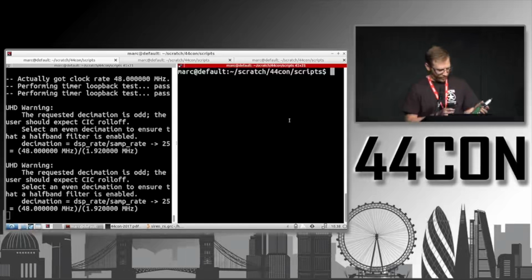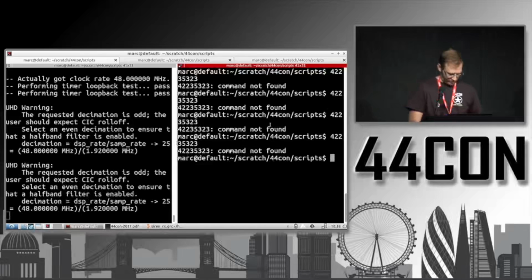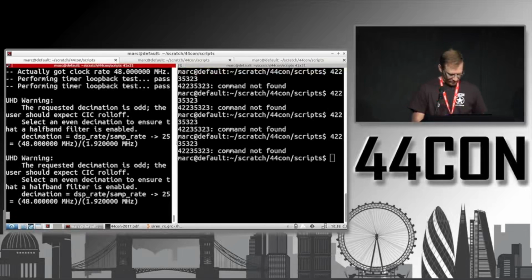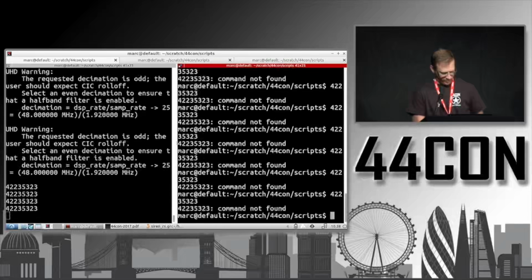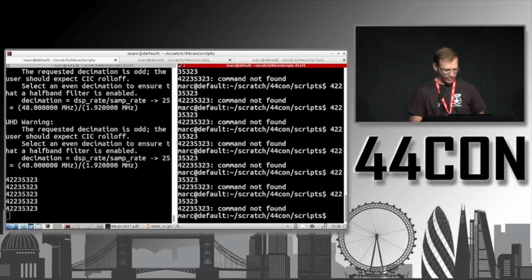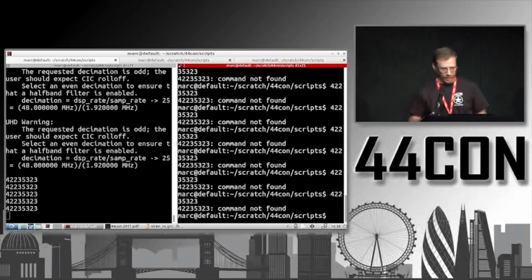Okay, so I'll scan this barcode here. Check the terminal. Okay, there we go. So now we're having the barcode read, and we're seeing some of the time it's picking it up on the left with SDR receiver. And what's interesting here is that because this device is just a functional USB keyboard, and this is unencrypted, it should be vulnerable to keystroke injection if you know people with barcode scanners.